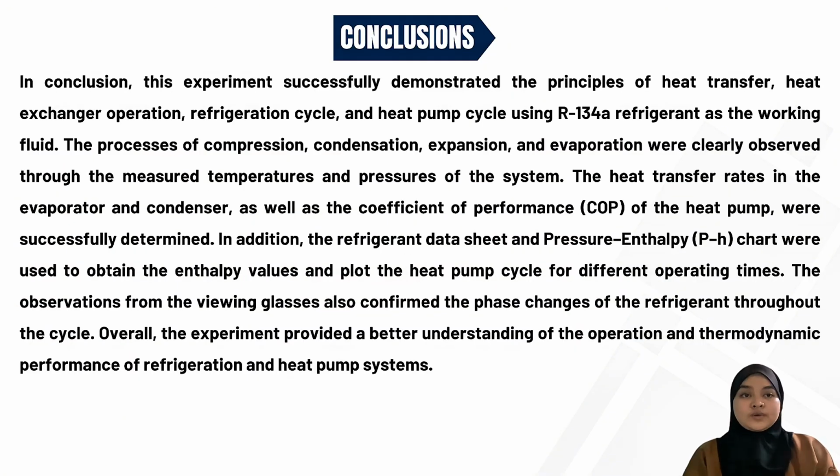within the system. In conclusion, this experiment successfully demonstrated the principles of heat transfer, heat exchanger operations, refrigeration cycles, and heat pump cycle using R134A refrigerant as the working fluid. The processes of compression, condensation, expansion, and evaporation were clearly observed through the measured temperatures and pressures of the system. The heat transfer rates in the evaporator and condenser, as well as the coefficient of performance of the heat pump, were successfully determined. In addition, the refrigerant data sheets and pressure-enthalpy chart were used to obtain the enthalpy values and plot the heat pump cycle for different operating times.